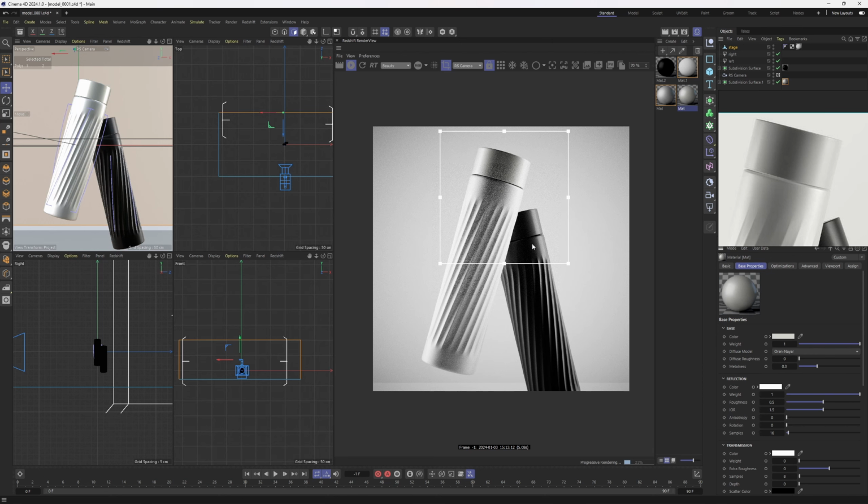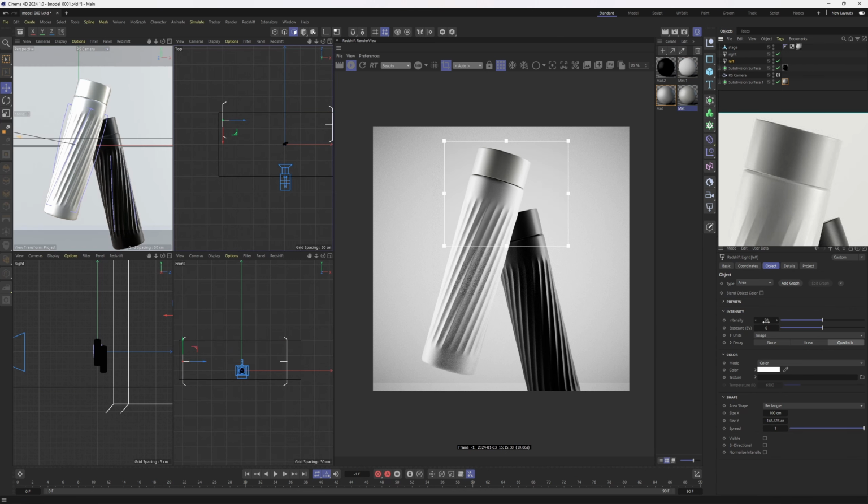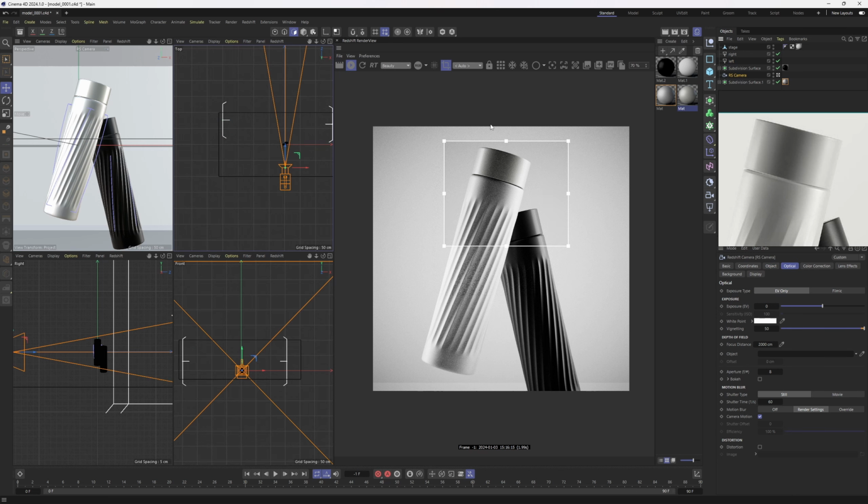Okay, now let me make a render region so that I can have an idea about the image quality, reflections, or the shadows. So I will click on that icon. I want to select my left light and lower down the intensity. I know this is gonna make the image quite darker, but I have still more options to alter the exposure of this image. So select the cam, go to the optical and set this to something like 1. Then let's render it again.